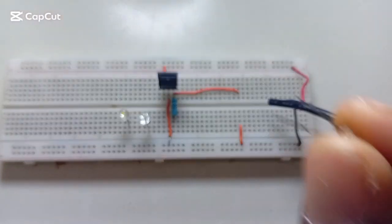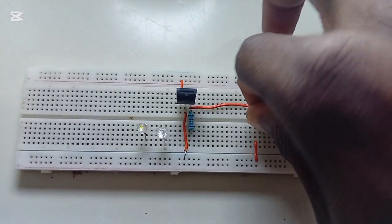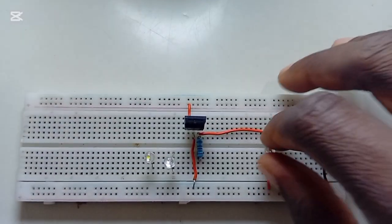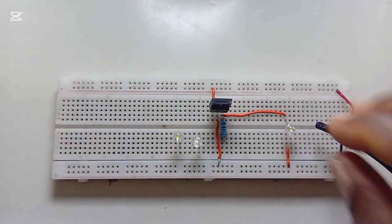I'm going to connect this LED without a resistor in series. You will observe what will happen to it. So let me connect. So I've connected the LED. Let me turn on the power. So you see it just light up and it went off.